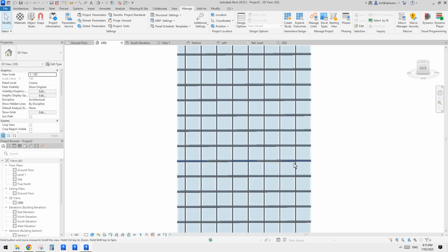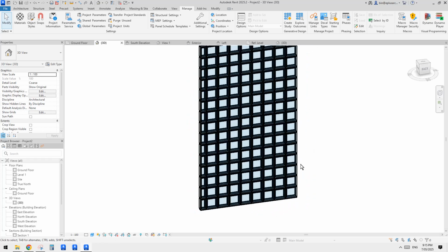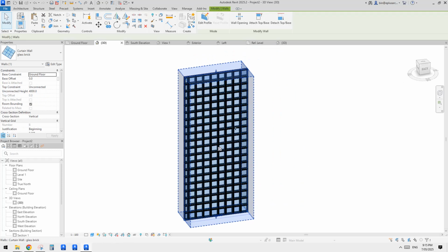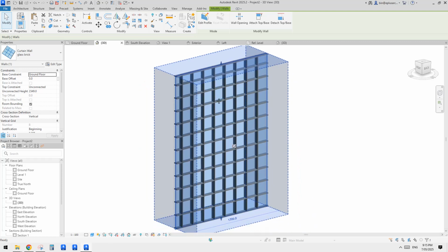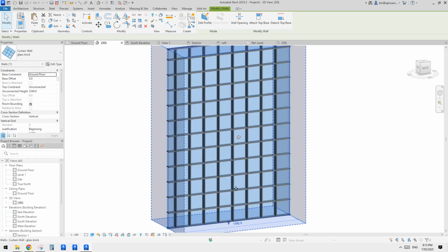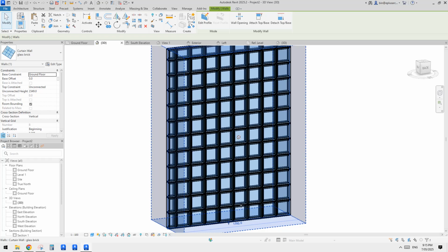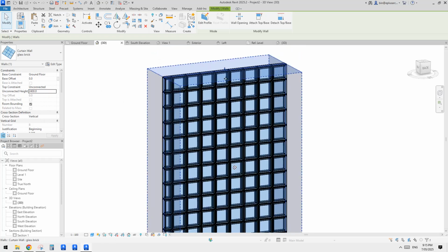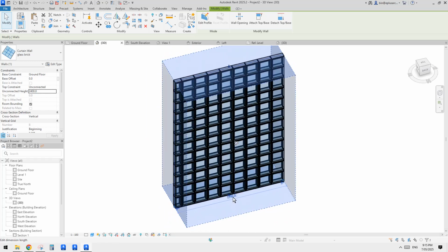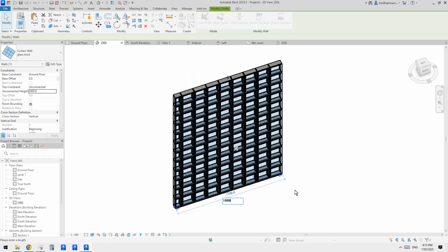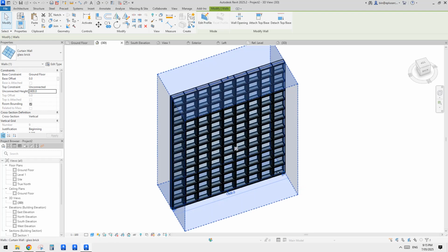Let me just drag this down a little bit. Yeah, probably you won't have half brick, but you might just need to do some calculation, like this is 190 plus 10 is 200, and then you just do a 2400 instead of that. Yeah, so you will have all 4 bricks, and then also you can do this to the width, like 200. So I'll just type 180. So we have 9 bricks. 1, 2, 3, 4, 5, 6, 7, 8, 9.